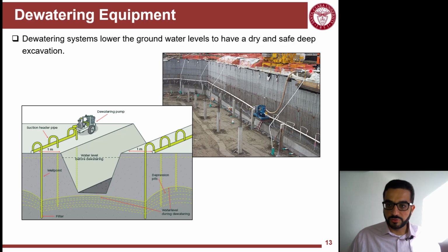So dewatering is required whenever you're digging below a groundwater level. It's always a question when you have an excavation, what's my groundwater level? And if you're gonna need a dewatering system or not.